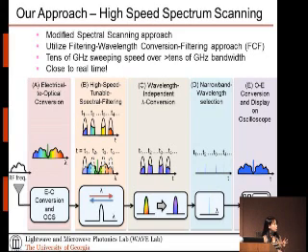And because they have been converted to the same color, what we need here is not a tunable filter, but a fixed wavelength narrowband filter. So fixed wavelength narrowband filters are out there already. It's just they're not fast tunable. So by combining all the information you've got here and launching it into an oscilloscope, you're able to reconstruct the spectrum like this. Okay? Right now they're of the same color, but you're able to tell which frequency is which by looking at the timing.